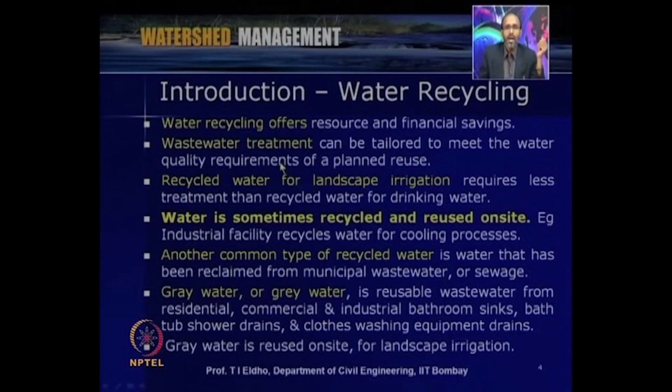So, when we look into water recycling, it depends upon the quality of the wastewater, what grade of treatment we have to give to that wastewater, and what purpose we are going to use that treated water for. Accordingly, we have to give appropriate treatments and identify the appropriate use. When we look into the literature, we can see that recycled water can be used for different purposes. Even with a complete set of treatment, starting from primary, secondary to tertiary, and treatment like ultraviolet or reverse osmosis, we can use it for potable purposes.